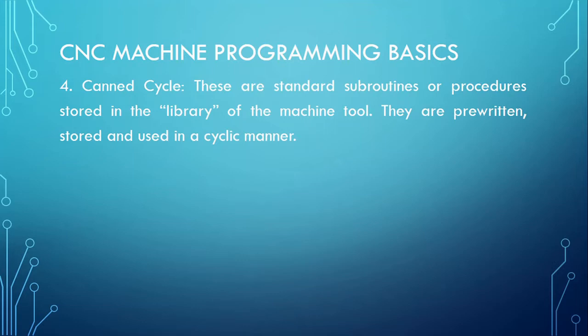Generating the part program for any part would run into a series of lines of part program codes. One of the ways to minimize the lines of code on your part program is to use the canned cycle. A canned cycle can reduce your lines of code by as much as 10, 20, 50 lines. So the part program can be well detailed using a canned cycle. One canned cycle can take care of so many lines of part programs, and a lot of them are possible on the MCUs of machine tools.